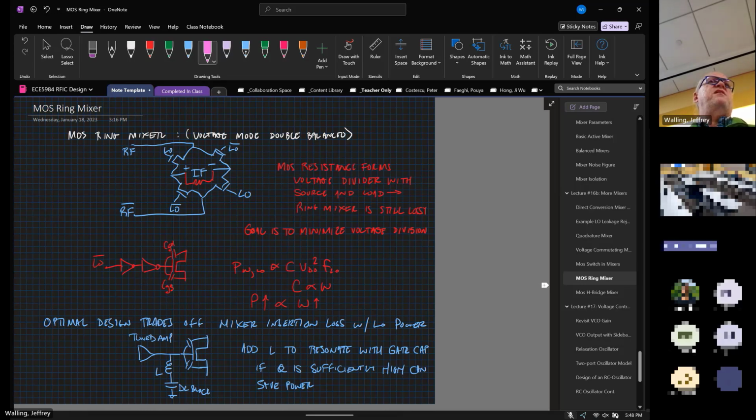Anymore, I would say most of the CMOS radios that I see nowadays use passive mixers. And I won't necessarily say they use in-path unless you define in as 4, which is a quadrature mixer. But there are a number of papers from ISSCC where I've seen them using 8-path filters, but I wouldn't say they're using them as filters.